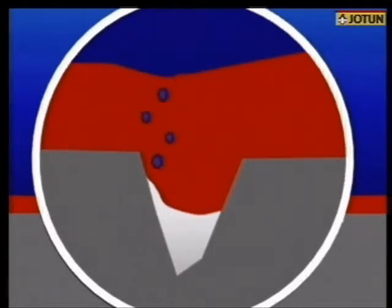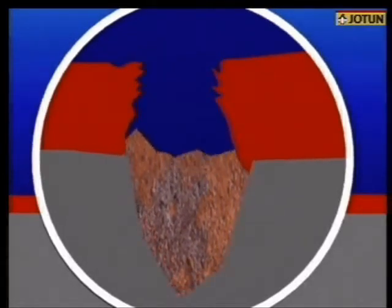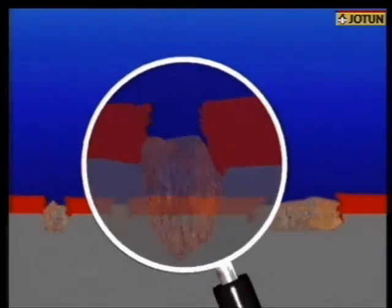On a surface such as this, the poor wetting ability of the roller will give holidays, most probably pinholes and areas with poor adhesion between the paint and the substrate material. These areas are weak points in the film, and after some time in service, blisters may develop. When they burst, unprotected steel will be exposed and corrosion will begin.